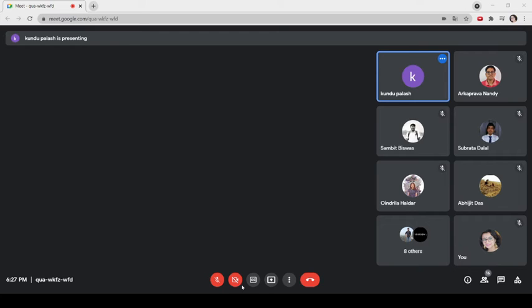So timer 0 has several modes of operation. That is, mode 0, mode 1, mode 2 and mode 3. Mode 0 means the 13-bit count mode. Mode 1 means 16-bit count. Mode 2 means auto reload mode, 8-bit, not 16-bit. Mode 3 means split timer mode.